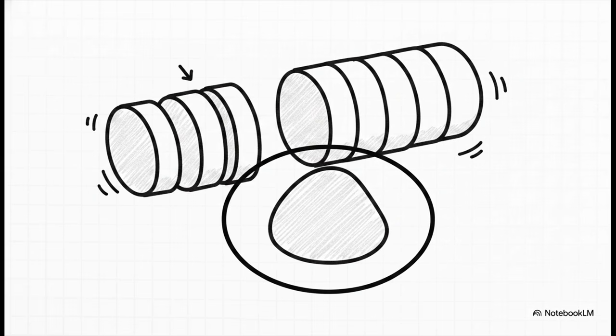That means each individual slice can actually have a slightly different center point, as long as the surface of that specific slice is perfectly sandwiched between its own two concentric circles. So it definitely catches if a slice is oval-shaped or egg-shaped, but it doesn't care at all how those slices stack up against each other.